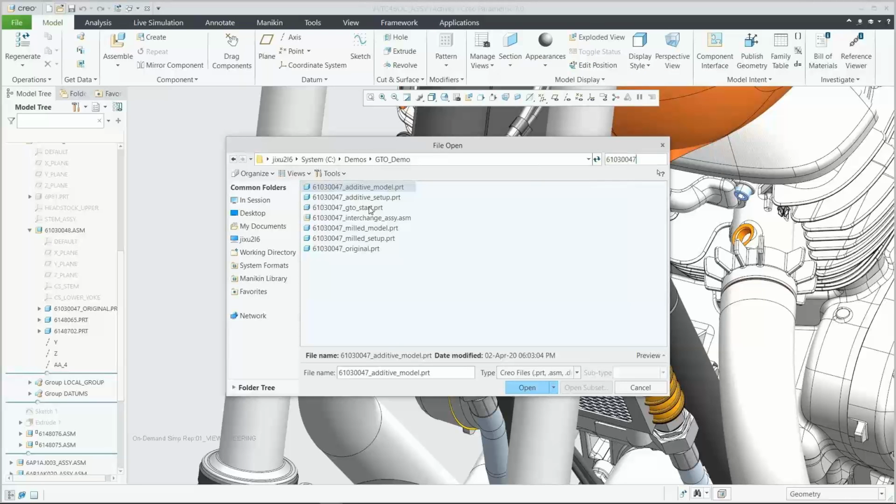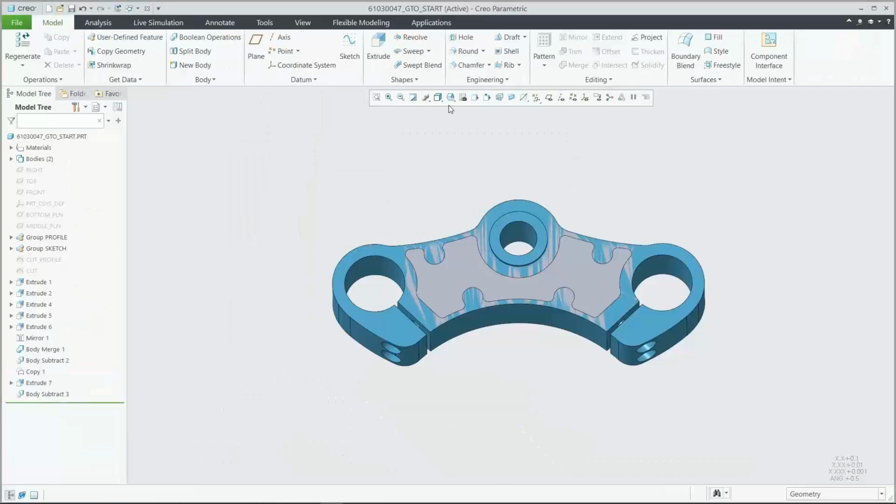Right, so here we can see I have that same yoke part, but a little bit more simplified version of it. So this is going to be the base I'm going to begin to work off of. And you can see here that I start with just an overall envelope. This is where we're really going to be an envelope or just a container for everything we're going to be designing around today. And then on top of that, we also have another body that is our preserved geometry. So this is all the geometry that once generative design has gone through and created something, it is for sure going to include all of this geometry. So that's something that we want to lay out before hopping into the study.